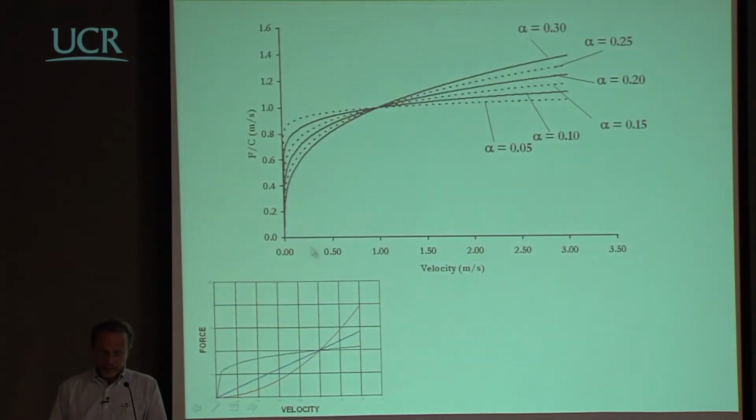Essentially, what happens is what's shown here. If that exponent is larger than 1, you have a plot of this sort, so you're going up rapidly. If it is much lower than 1, you are coming in this way, so you have something which is rapidly flat. So you look here, you take, for example, alpha equal to 0.1. Remember, this is force versus velocity. It's not force versus displacement. So it's something that we're not used to using in a structure.